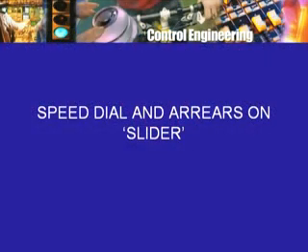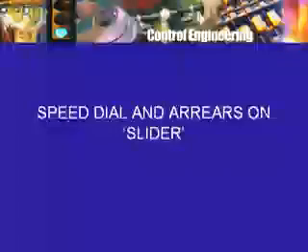Think about this. Of course, the operator will not have to do this thinking. He can be trained, or by using experience, he can figure out that if the speed goes down, then the slider of this resistance or rheostat should be moved to the left or should be moved up or down. And so in fact one can have arrows there or some indication there like increase and decrease. So the operator simply looks at the background where this is written against the slider, and one way movement of the slider says increase the speed, the other says decrease the speed, so that is what he does.